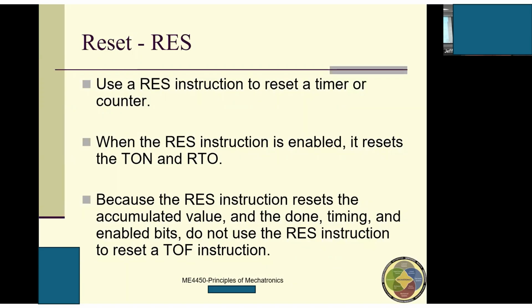If I ask you guys why it is highly recommended not to use RES to reset the TOF, and you give me a correct answer, the key is that TOF is triggered by a true to false transition.